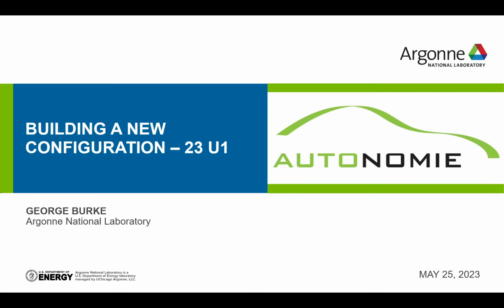And in today's video, I'm going to show you how to create a new powertrain architecture or configuration using Autonomie. For this demonstration, we will be using the 2023 U1 version of Autonomie and the 2022B version of MATLAB, but it can be done in any other previous version of Autonomie and MATLAB. So to get started, let's go into the Autonomie GUI.